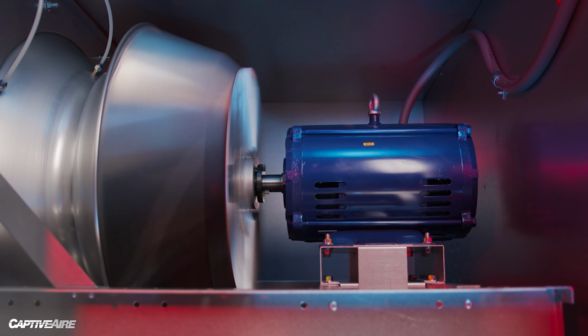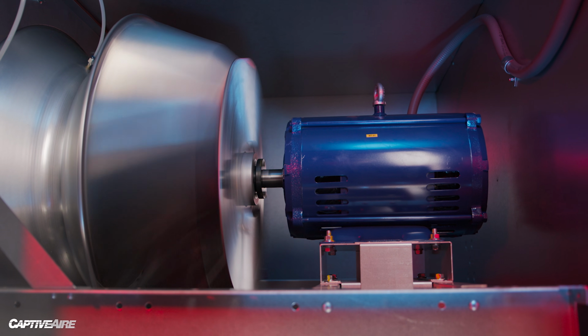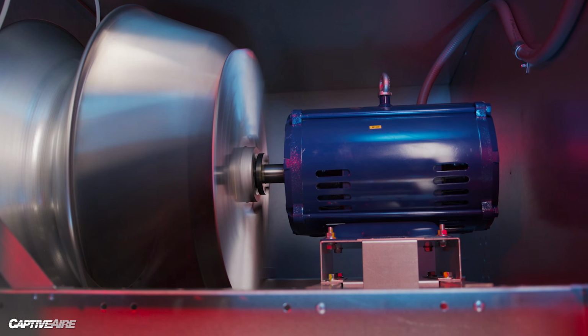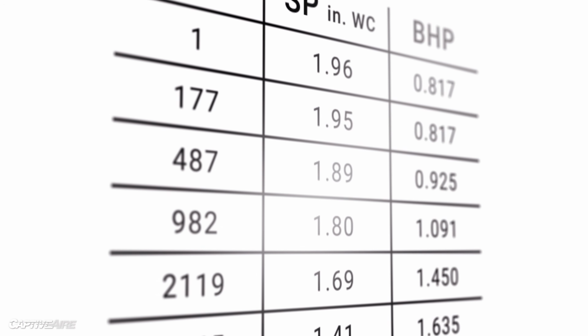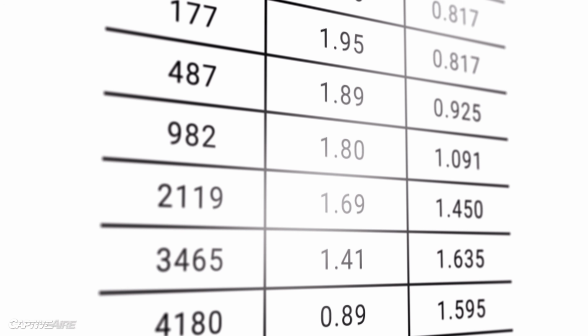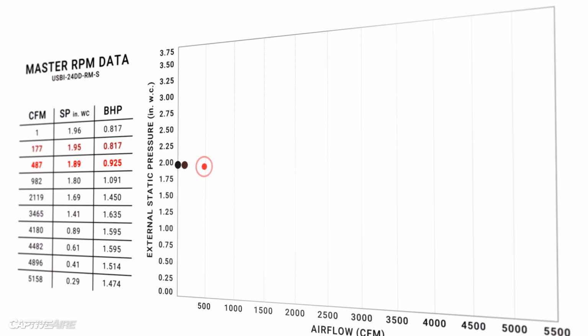How do you create these fan curves, right? Can you use math to just create a fan curve? The answer is somewhat. You have to start with a tested set of data. So you have to develop what we call a master RPM curve first.